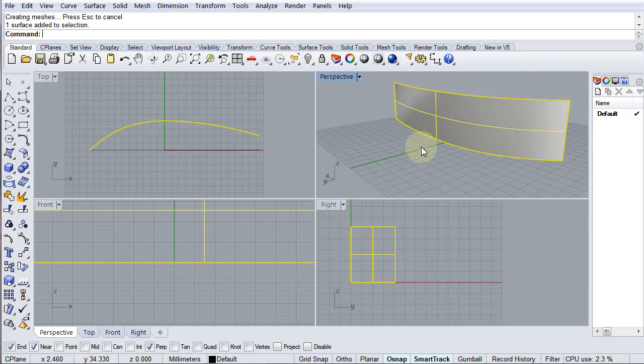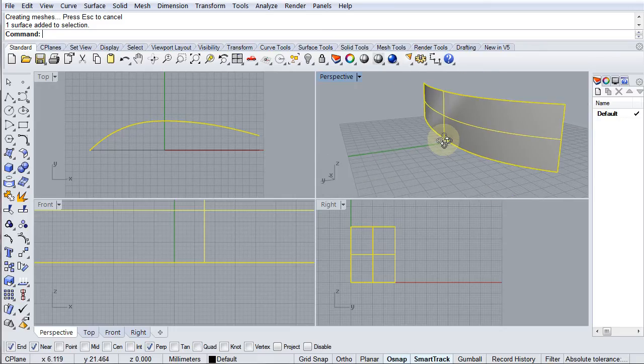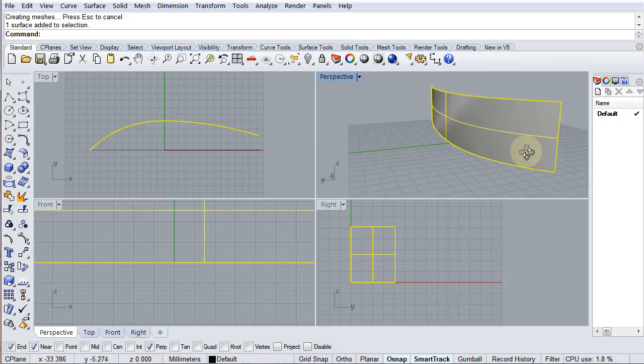It's an extruded surface. If you notice, if I press explode here, you'll get a second curve appearing, and that is now a true surface, and it's a fully defined surface, which means it's slightly larger in the file size than the previous extrusion. The reason for that is so that Rhino can work with larger numbers of lighter objects like extrusions without having to continually turn them into full surfaces. So that's now a full surface.